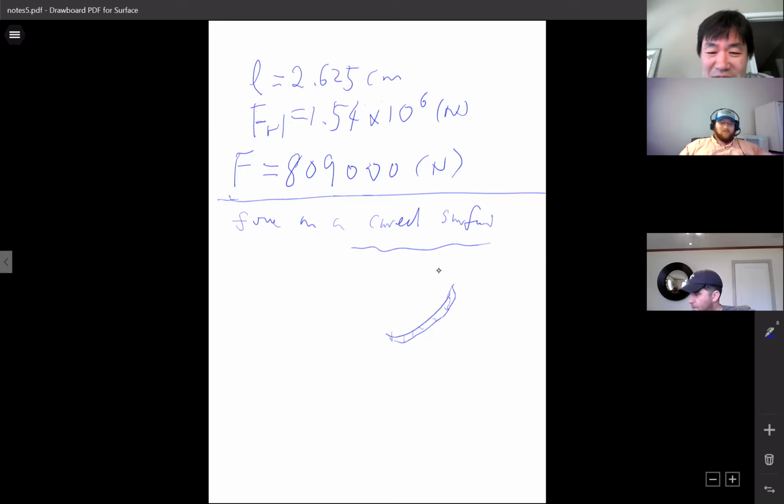So what is the hydrostatic force? I think some of the students are confused, hey, both sides have hydrostatic force, right? So we don't want to look at both sides. If you look at both sides, then the difference becomes buoyancy. Let's say one side of the surface. Let's say the thickness of the surface is infinitely small, so both sides have the same force applied to it.